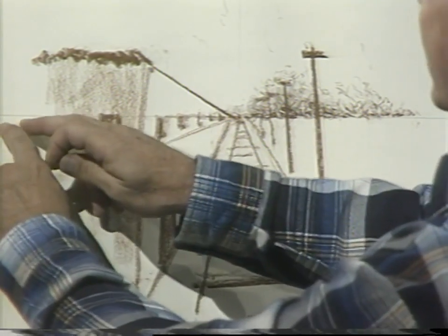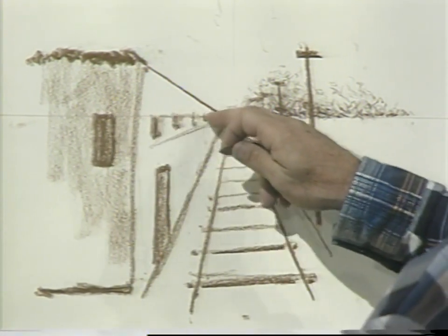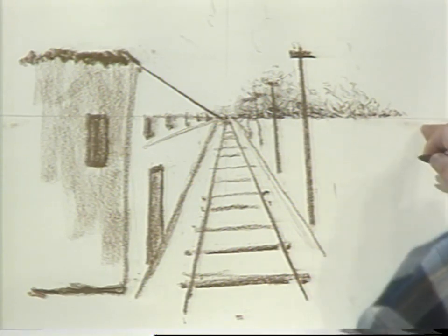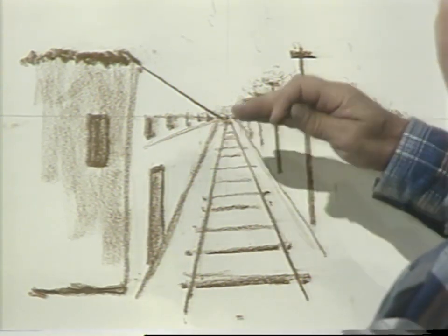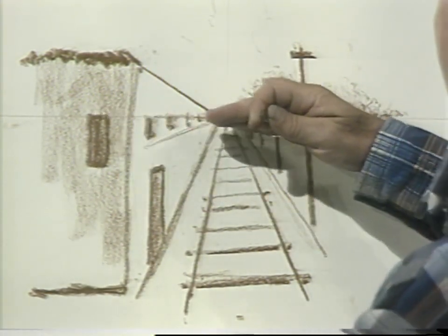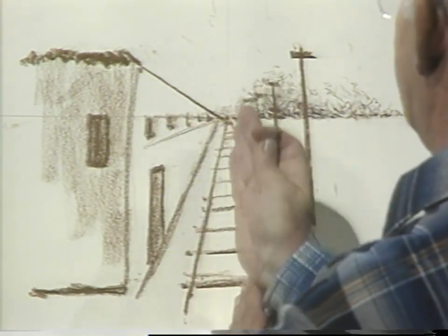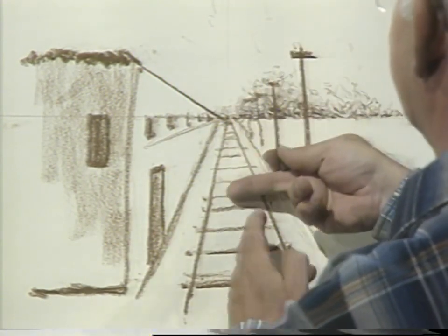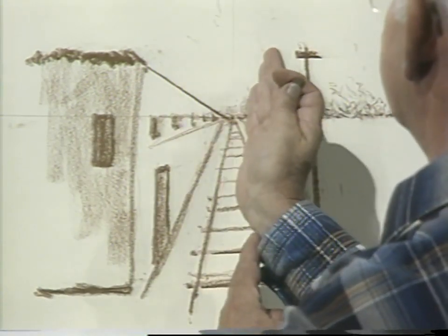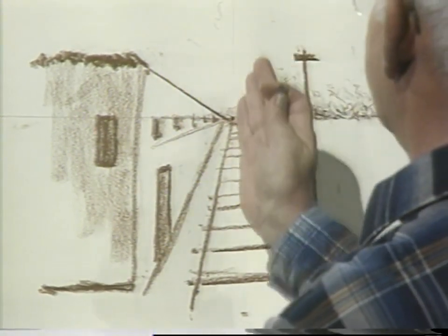I started off with an eye level, sometimes called the horizon line, and you can still see the eye level here. That's very important. That's probably the first step in drawing a perspective or in drawing. We determine where the eye is viewing and at what level. Now my eye is at this level. Then as I come along the eye level, I must determine a center line of vision. And you can see a faint line here that I left to show you. So along this eye level, my eyes are at this level and they stop at this point. That's called a focal point there. And here's the center line of vision.